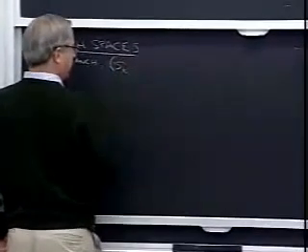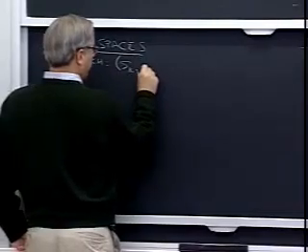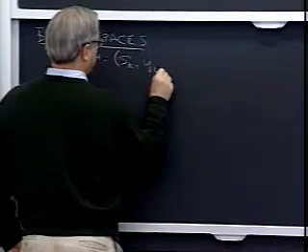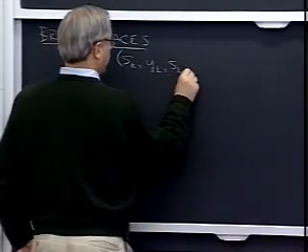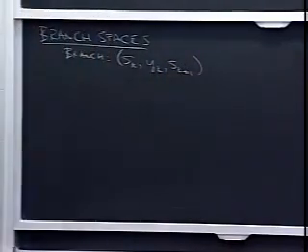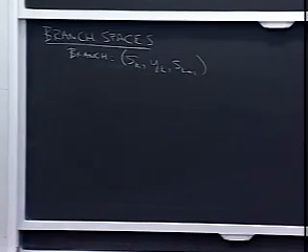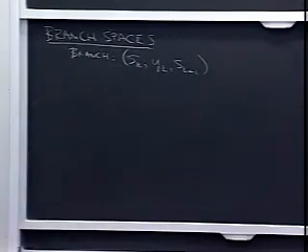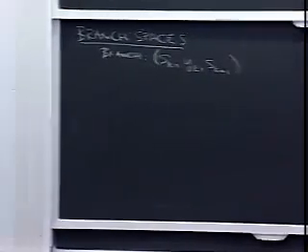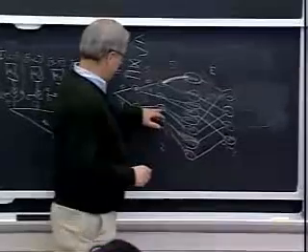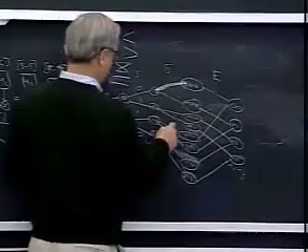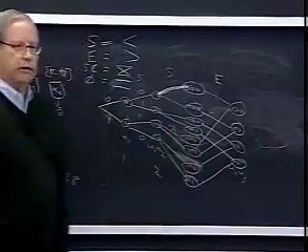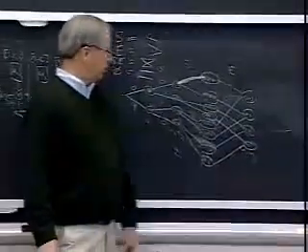What do we need to define a branch? We have an initial state, the code output at time k, what are we calling that? Y at time k, and the next state. So it's that triple. Again, this is linear system theory: state, output, next state. Okay, those are the three things that define a branch. This branch is state 1, 0, output whatever it is, yk, and next state 1, 0, 0. And that differentiates it from this down here.